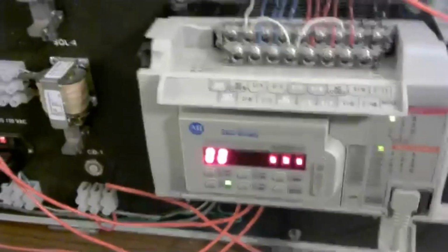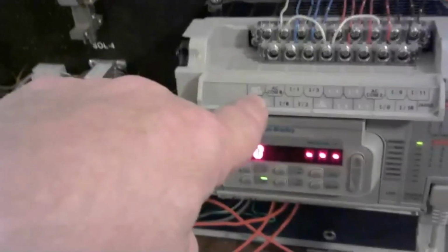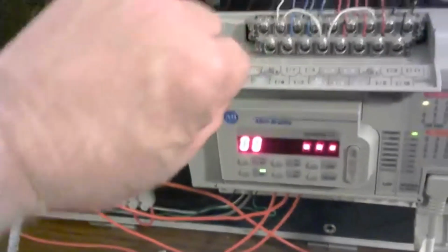And so that's something that would be unique for each type of PLC. You got to put commons on wherever it's asking for them, or hots. For the inputs, these sections have to have some commons in there, and then you're bringing hots in for each point.